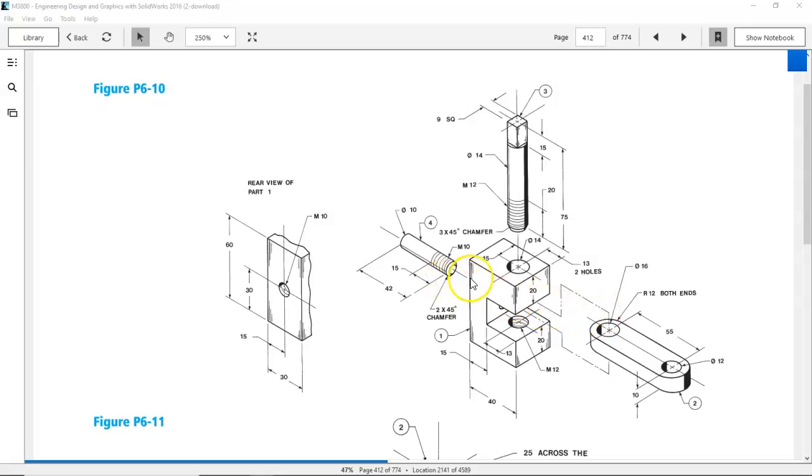As I mentioned in the overview, my initial strategy is to draw this C shape, get that geometry in. Notice the symmetry. And then the overall height, let's see, looking for the gap. Since that is 10 millimeters, we're going to go line to line and then we'll decide what kind of clearance, since I don't see a 10 millimeter gap in there.